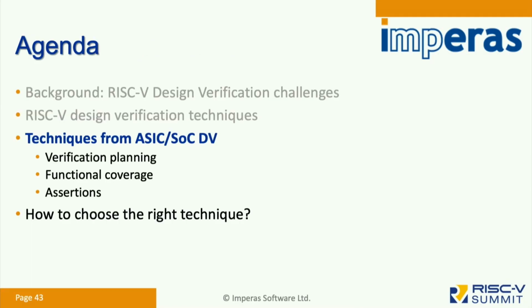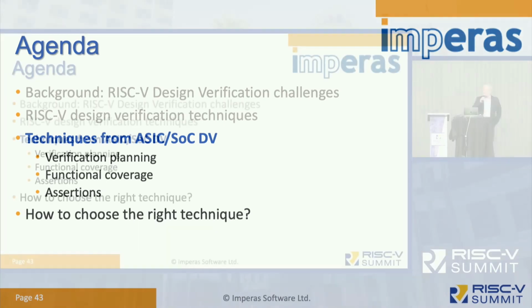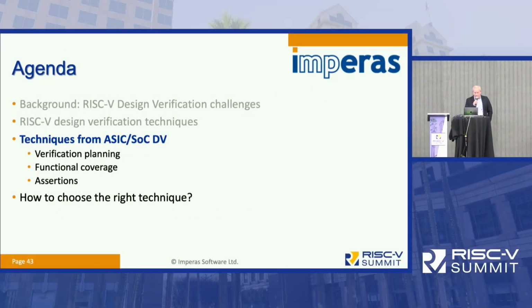So hopefully that made some sense. It can be a bit overwhelming when you see this for the first time. For me, I've been working on this for nearly 3 years, so I know it quite well. But this has been crucial in a lot of the verification we've been doing with designs where they need to ensure that the handling of the asynchronous events can be used as part of this flow, in order to make sure that the RTL is meeting the ISA specs.